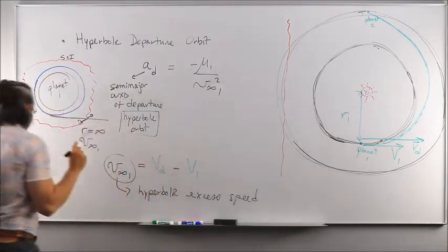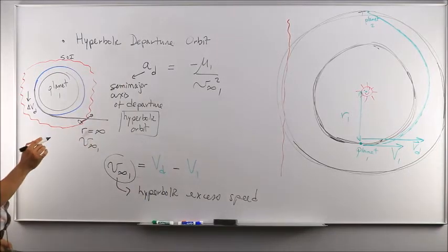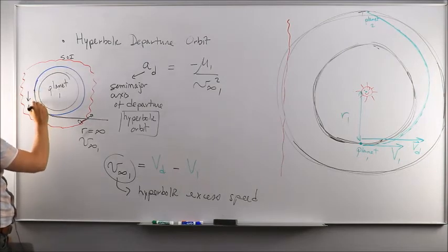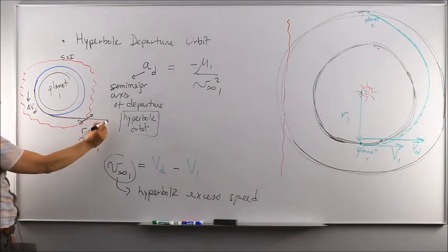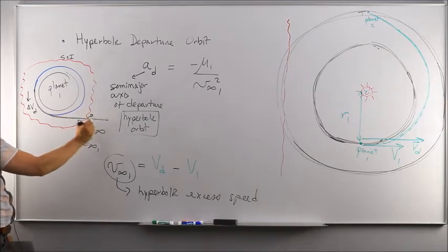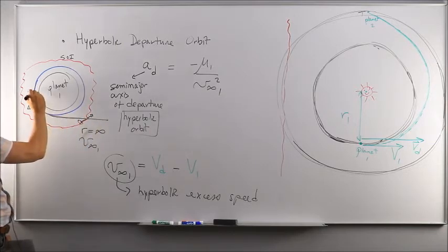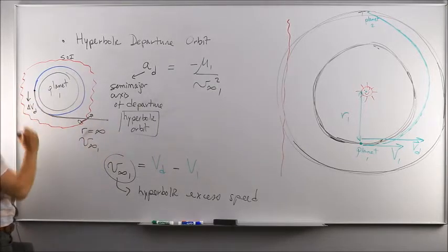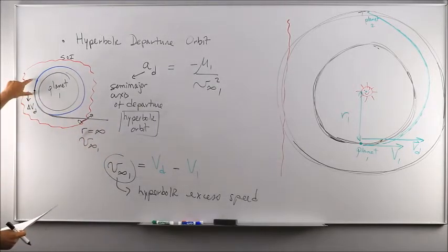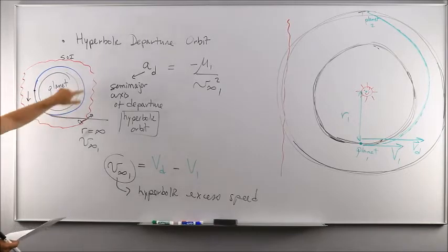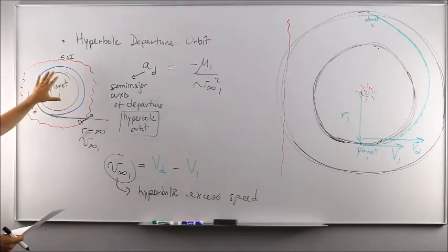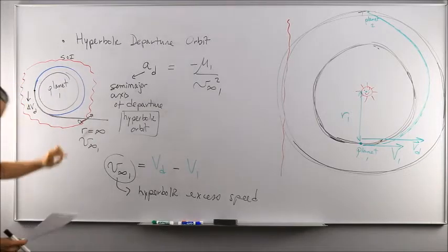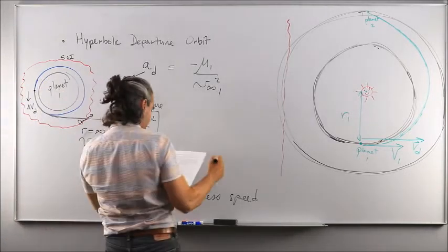And now, knowing that the actual delta V maneuver takes us from this parking orbit to this hyperbolic trajectory, then we need to figure out the speed along this hyperbolic trajectory, specifically at its perigee, because the point at which we're going to apply the maneuver along the blue LEO parking orbit around planet 1 will turn out to become the perigee of the hyperbolic transfer orbit.